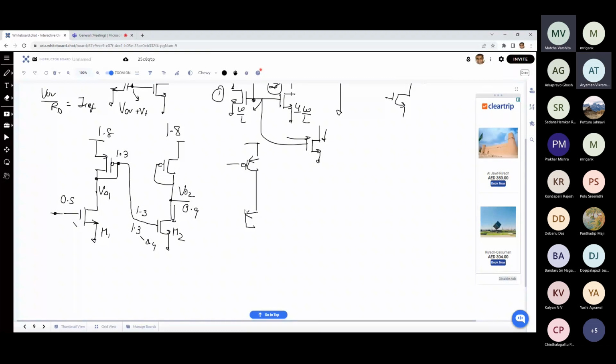So then that PMOS also has 0.1 volts overdrive because we want those. If I do this, then it is safer, because now this is matched. This is PMOS, and this is 1.8, and this is also getting almost similar VSG. So from a DC point of view, this is much safer because the DC bias gate voltages are well established.